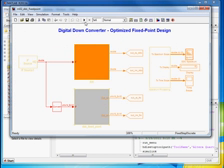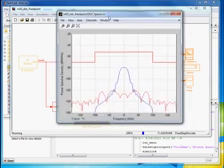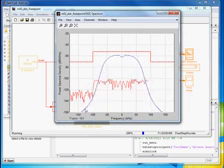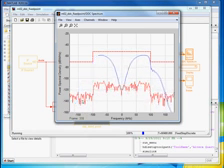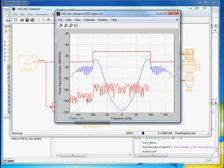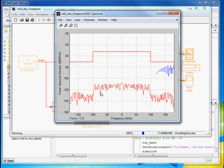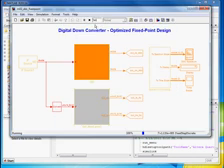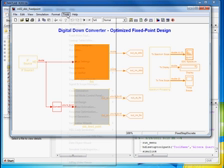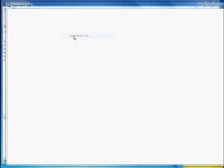So let's go ahead and simulate that and see how we're doing in this process of going from floating point to fixed point. And as we see here, the blue line representing floating point and the red line representing fixed point are very, very different. So there's clearly a problem with what we've done here in going to fixed point. We've lost fidelity in a dramatic way. So now what we're going to do in order to diagnose this is bring up the fixed point tool.